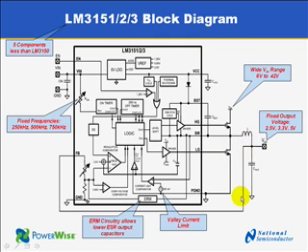The resistive divider to set the output voltage is saved, as we have fixed output voltage options. The resistive divider is transferred into the device. The external soft start capacitor is saved, as the soft start is realized by an internal soft start circuitry. The external R-on resistor is saved, as it is transferred to an internal R-on, which gives a fixed frequency.